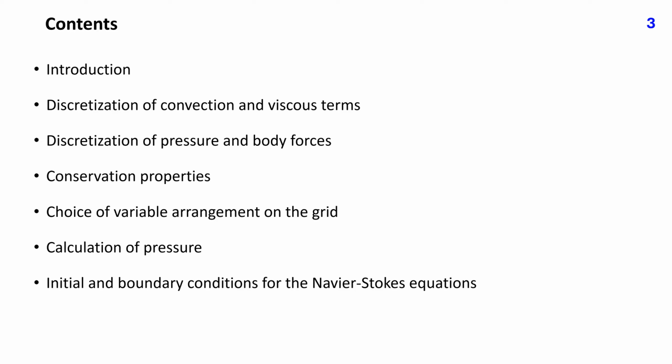Viscous terms in the momentum equations are also more complex than diffusion terms in the scalar transport equation, and discretization of pressure terms requires special attention. Such terms are not present in the scalar transport equation. In addition to momentum conservation, we should also try to conserve the kinetic energy, but there is no independent equation for kinetic energy. It is also not obvious how to compute the pressure in an incompressible flow.